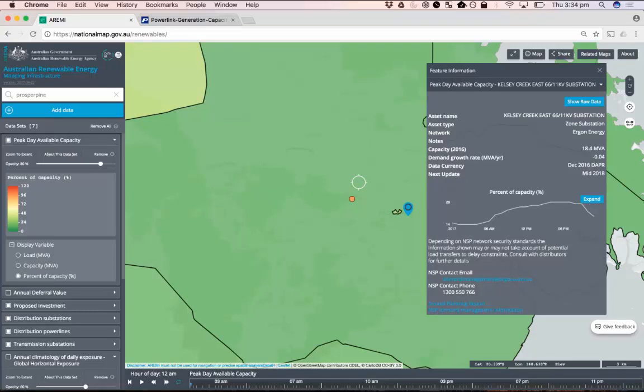It's actually quite a broad peak, which is indicative of a transmission network issue rather than a peakier distribution network issue. And so that extends into the evening, which might mean there might be a role for battery storage, or it might actually be something that's potentially more suitable to a bioenergy dispatchable generation case.